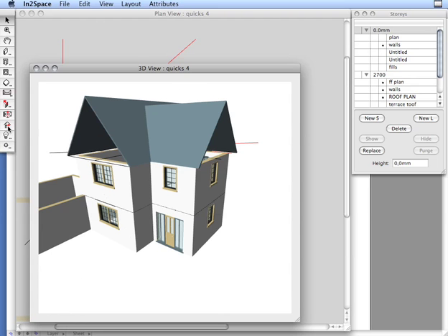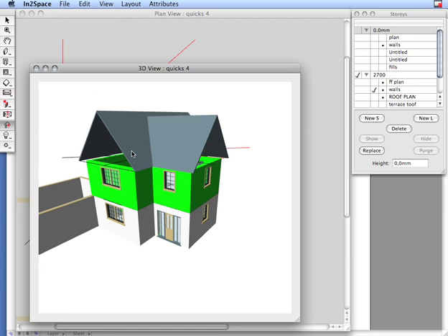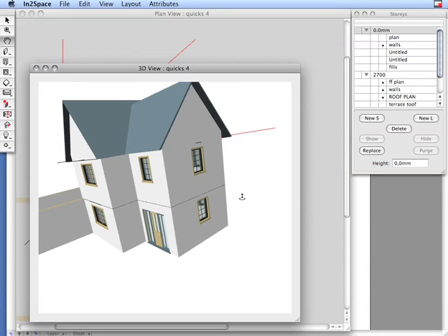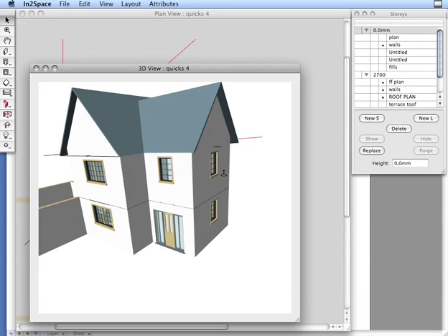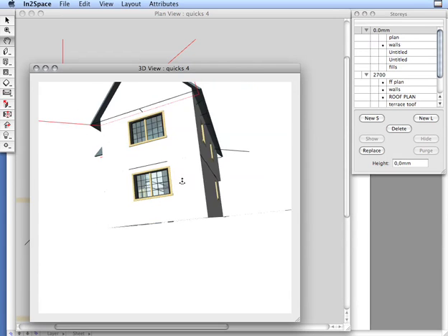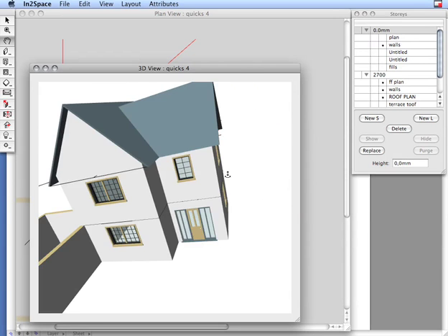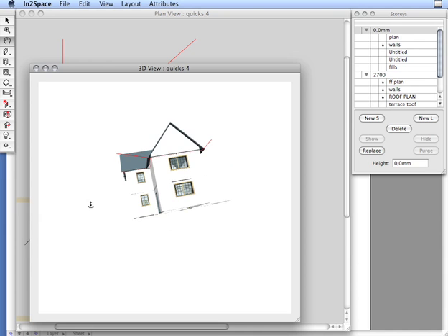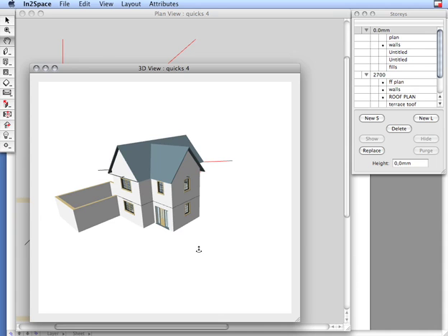And you'll see, using the extend wall to roof tool, system was thinking a little bit then. I can show you that we've extended the walls to the roofs all the way around in one automatic click of a button. Fantastic, very powerful tool. And there we have basically a shell of our building constructed.